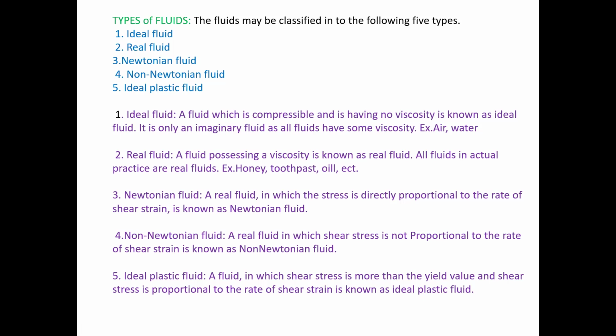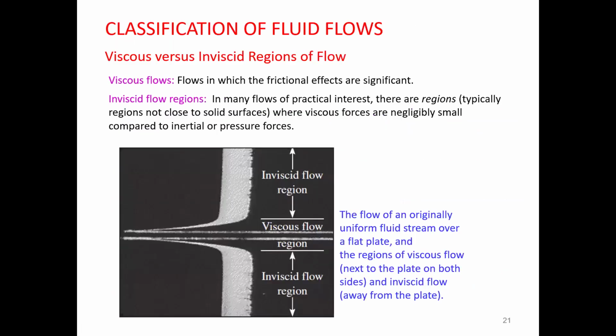Ideal plastic fluid, in the sense, is a fluid in which shear stress is more than the yield value of the shear stress and it is proportional to the rate of shear strain. It is known as an ideal plastic fluid.